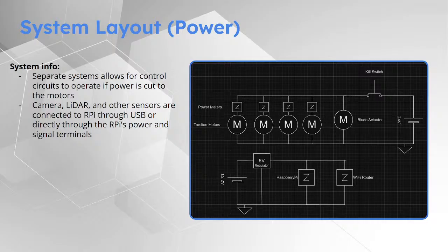Yeah, so if you single point ground, I think you're going to have some noise, but what you really need to avoid is having any ground loops in the system. So you're tying these to chassis, as far as the motors are concerned? Yeah, we were looking into running a conductor outside of the box, tying that to chassis too, as long as they're all on the same ground. Yeah, the most important thing is addressing the return path.